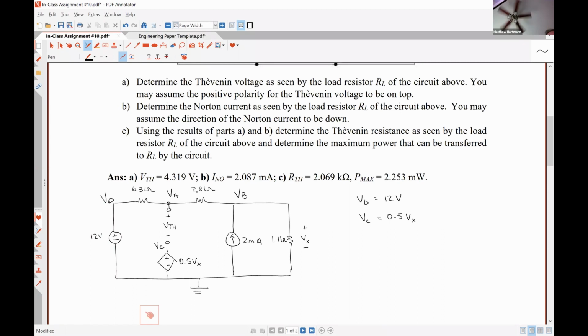So it's the nodal voltage associated with the positive polarity terminal, which is VB, minus the nodal voltage associated with the negative polarity terminal, which is ground or zero. So VB minus 0 is equal to Vx. Yeah, that was my fault. Sorry, I misheard the question. No problem. So VB is equal to Vx. So that means VC is equal to 1/2 VB.